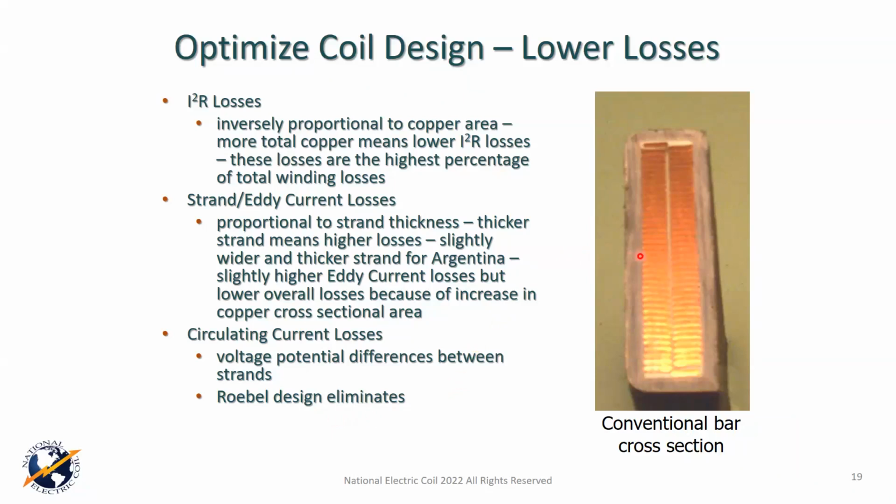Again, we look at the thickness of that insulation, and one of the things I hate about virtual is it's hard to ask you questions. But if I had to ask you what's important about the thickness of that insulation, I would hope you would tell me it's the volts per mil, which is the ground potential voltage versus the thickness of that. As a general rule today, 65 is a nice number, but there are a lot of designs running in the 70 to 72 range. The more you can keep that volts per mil lower, the less voltage stress you have on that ground wall. So I just wanted to reinforce that point again.